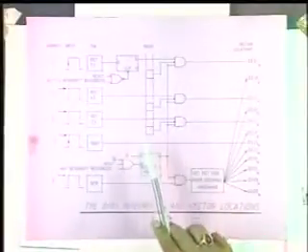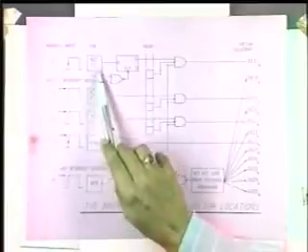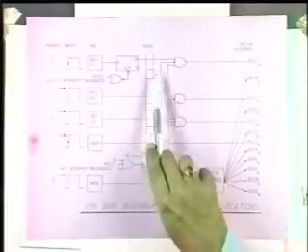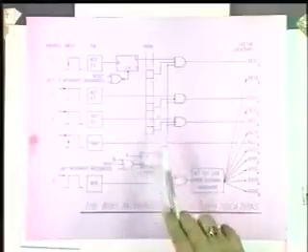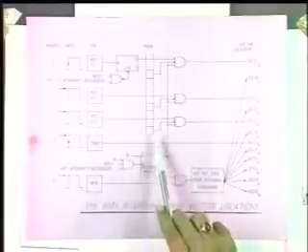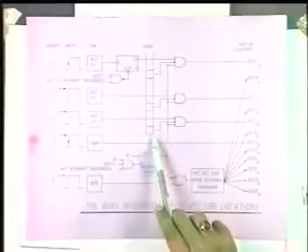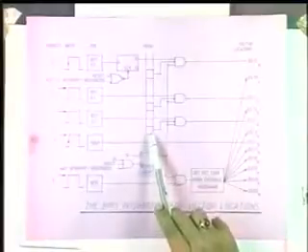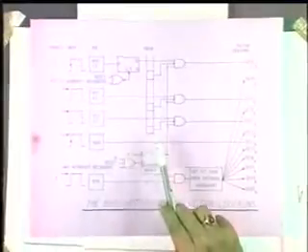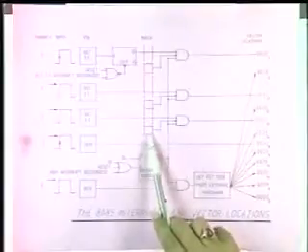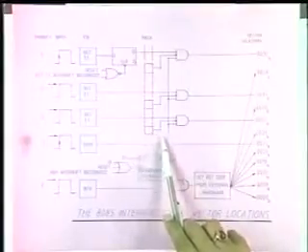That means if this is on, then only the corresponding flip-flops will be energized. And then we have another, what I show here in the mask. These are the mask registers, which are inside the CPU and which can be set or reset by using special instructions called SIM, set interrupt mask. It can be read by RIM, which is called read interrupt mask.